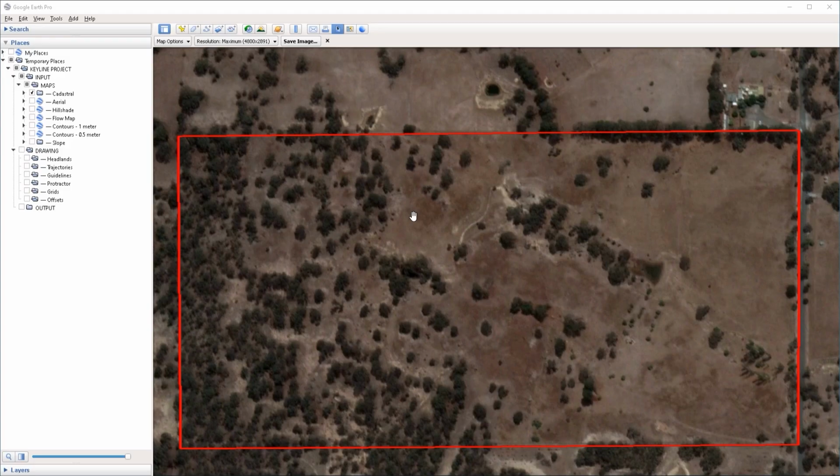For now, for our example project, we're going to assume that the headland width is going to be 10 meters and it's going to be a fixed width. That is, we're going to apply the same headland width all throughout the site. But headland width can vary, and this is again something that depends on the context of your project. For example, headlands that run parallel to a fence are not necessarily as wide as headlands that run perpendicular to a fence, simply because in the latter scenario you need more space to turn machinery.